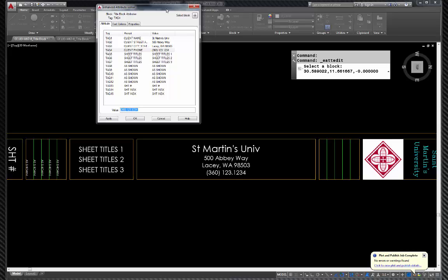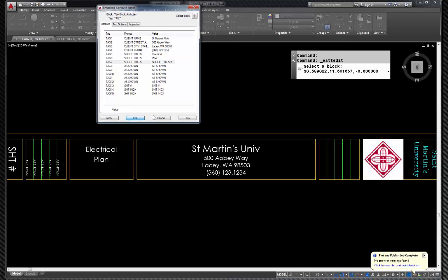Okay, so I'm going to skip the phone number, hit enter again, and I'm going to go to sheet title. This one's going to be electrical plan, and then one more, and then I'm going to delete that one so it doesn't show up, and then I'm going to go OK.